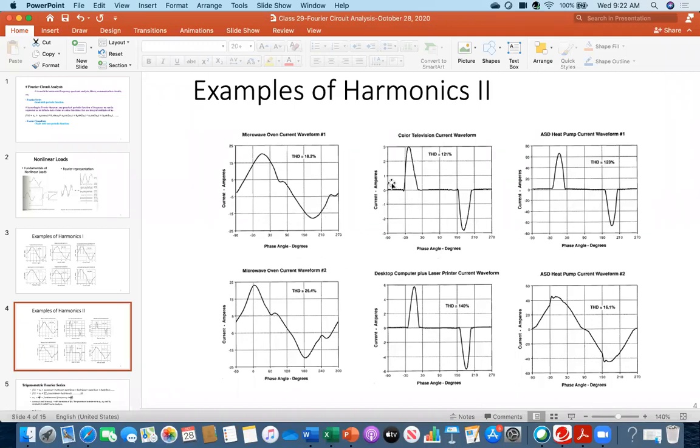You look, they are periodic signals. They are repeating after a certain time. You see this signal, it goes, and then again it will be like that. So they all look like periodic signals and look roughly sinusoidal, but not purely sinusoidal. There are harmonics. Harmonics means there is higher order frequency beyond 60 hertz. Therefore, in these cases, you have to apply the Fourier technique. So these are all realistic examples.